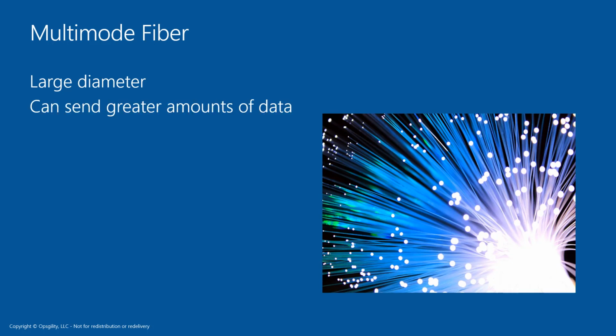Multimode fiber optic cable has a larger core that allows multiple modes of light to send through data. Because of this, the number of light reflections created as the light passes through the core increases, and that creates the ability for more data to pass through at a given time. However, because of the high dispersion and attenuation with this type of fiber, the quality of the signal is reduced over long distances. This application is typically used for short distance because of that.